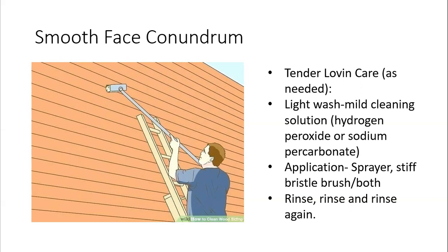If you want to keep it looking wood, beautiful and natural, you're going to want to wash it down once a year. All right, wash it down like a car. Use oxygen bleach. That's how we do it. Figure a sprayer and a brush application method. You just put that oxygen bleach on there, kind of brush it in, let it sit 20 minutes or 15 minutes, do its job, rinse it off. Typically, that's all you're going to have to do again. If you are a do-it-yourselfer, the thing to remember is rinse, rinse, rinse. So anything you put on that wall, rinse it off very, very well.